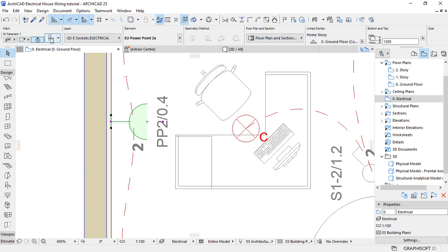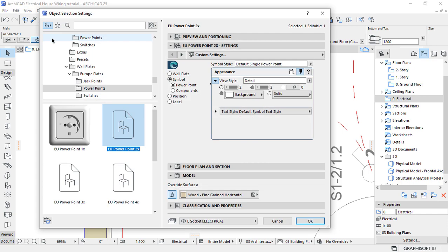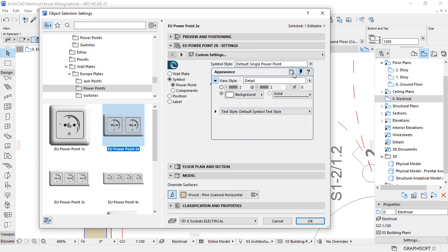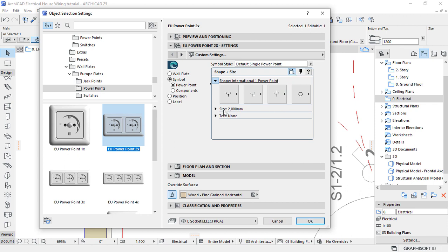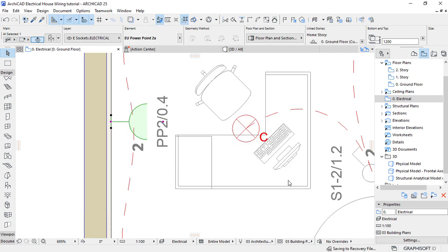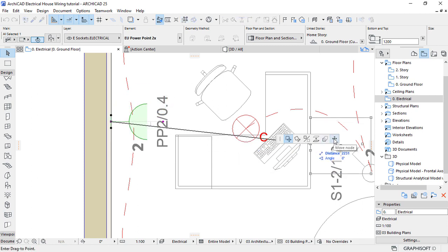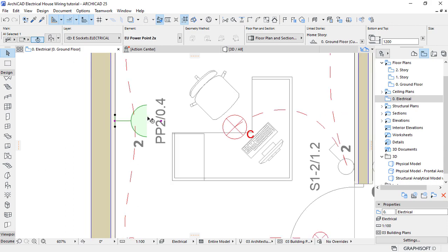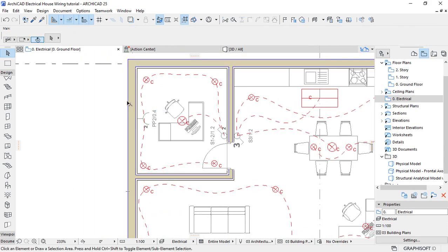curve element, let's go back to its options, to its settings, and then under the 2D and size, I think instead of having 1.2, let's leave it on 0.6, which is 0.60 millimeters, and then hit OK. Oh, it didn't change. Maybe we can modify it by stretching it using the move node. No, it can't work. Okay, let's leave it the way it is for now.